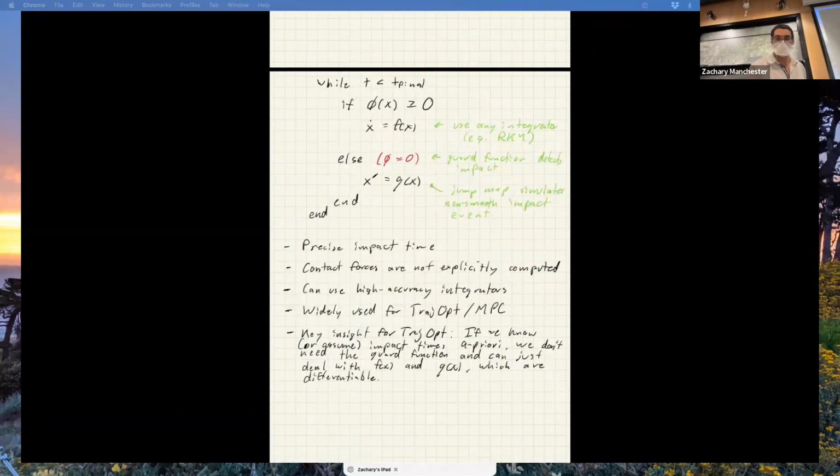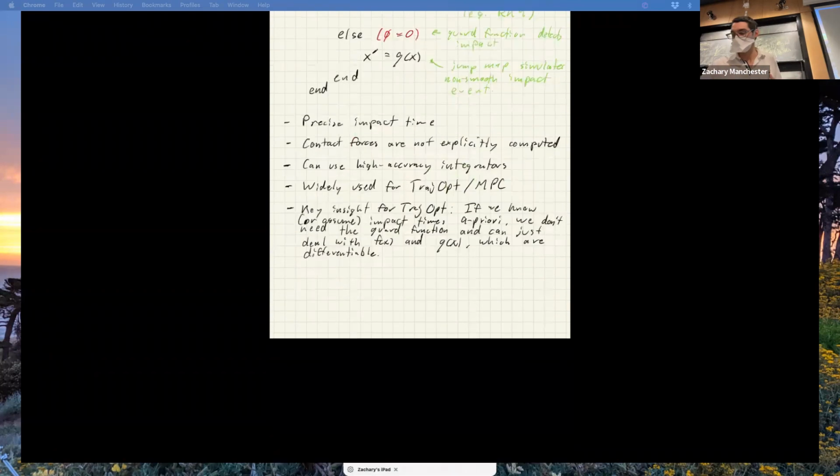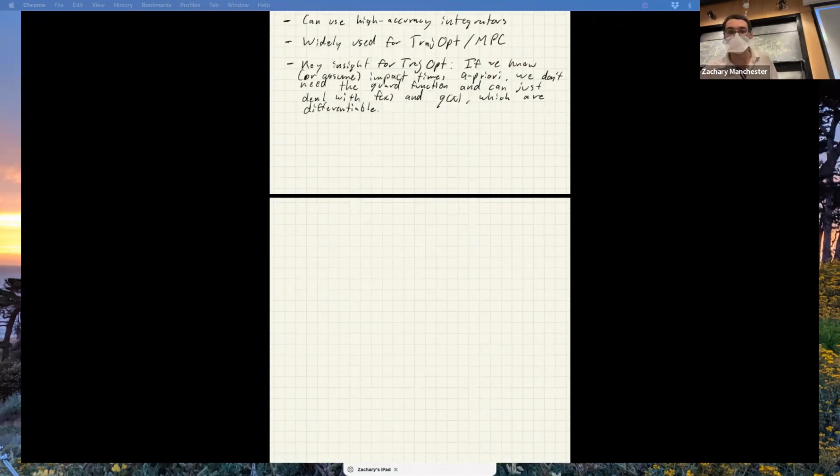Hooray. So now we're going to go ahead and do the trajectory optimization thing using this hybrid setup. And we're going to do this on the simplest legged robot there is, which is kind of the monopod hopper. Has anyone heard of a Raibert hopper? Maybe kind of. This is a dumbed down version of this, a dumbed down 2D Raibert hopper.